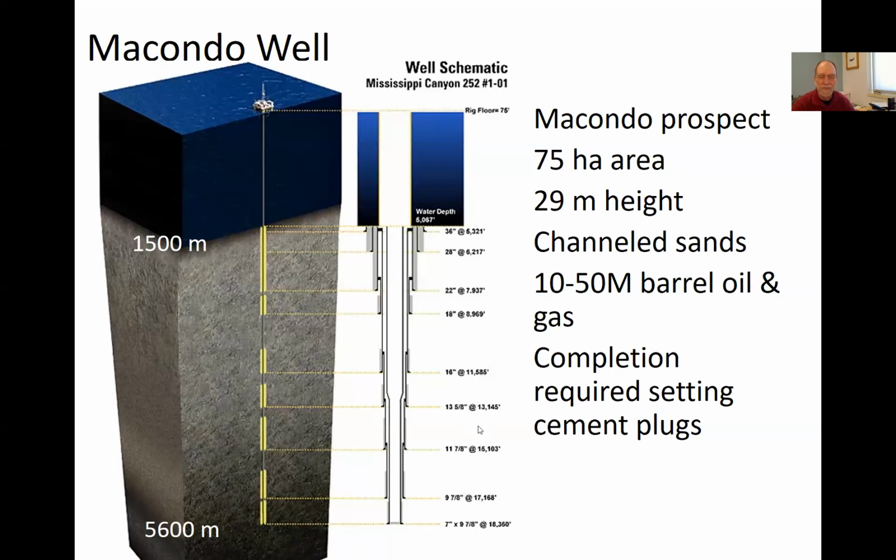Well, because this well had been so difficult to drill, and because they had found such a nice reservoir with this first well, the usual practice is that before they leave, they fill the whole well up all the way to the bottom with cement. So they would pour in cement and fill it all the way back up to the mud line to absolutely, totally seal off the reservoir and prevent any oil from escaping. And that's called shutting in the well, or cementing in the well. And so that would have been the usual practice to do this.